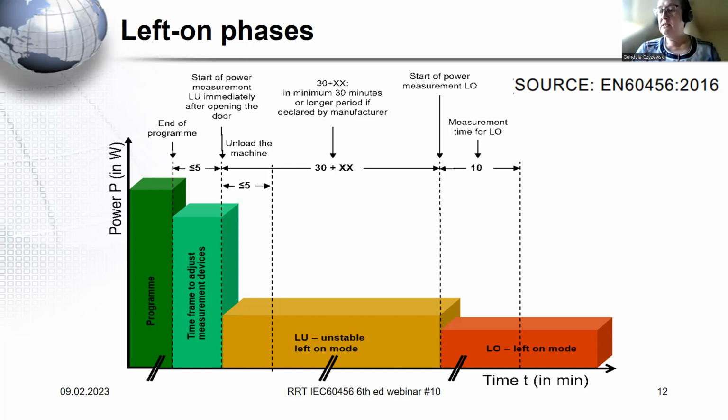There are other IECs referred to in Annex L, for instance, IEC 62301. This is quality requirements for the energy measurement, and you would need to consult that to find appropriate equipment for the measurement of these small energy consumption modes. And you have another IEC that you may want to consult in case of network appliances. This is IEC 63474 about network standby. Those standards will give you further hints what you need to consider to have the appropriate equipment for such measurements.